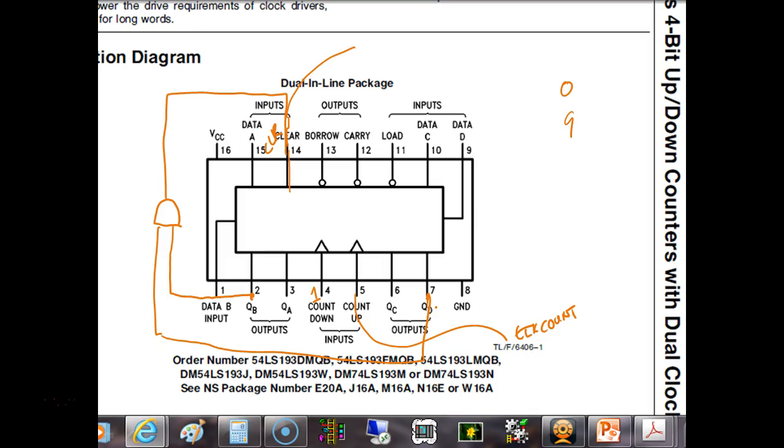No, it's still digital. We're just talking about digital now. So in PLCs, when you program a counter, you just put a little block up there. Well, the problem is that's done by a program, and in a program you have an instruction. If we looked inside the 1100, it tells us the amount of time it takes for every instruction. So we might look at a counter and it might say 20 milliseconds. If you try to give it a pulse past 20 milliseconds, it's going to give you the wrong count.